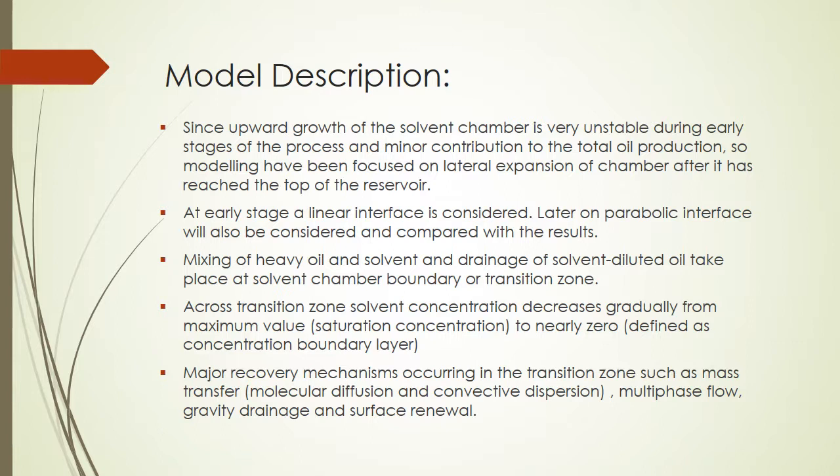At an early stage a linear interface is considered, but at a later stage we will consider a parabolic interface, and we will compare the results with the linear interface. Mixing of heavy oil and solvent and drainage of solvent-diluted oil take place at the solvent chamber boundary, which we call the transition zone.